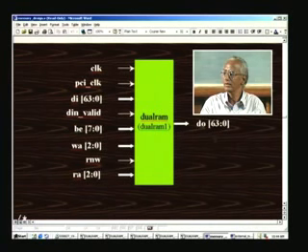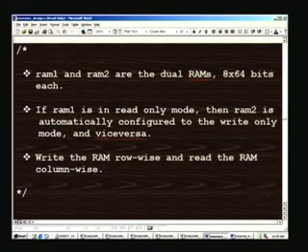That means to say, let us say there are locations LOC 0 through 7. We will be reading LOC 0 higher order byte, bits 63 through 56, and location 1 next the same number of bits, and so on. So what you write horizontally or row wise, you will be reading vertically, and that is the requirement arising from the DCT algorithm the speaker has developed earlier for DCTQ, which we will be considering later on. With this background, I think we will be in a position to